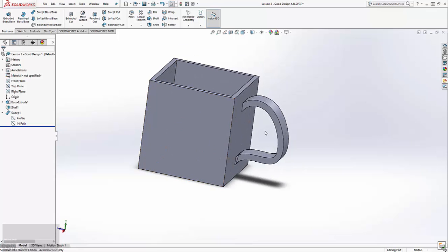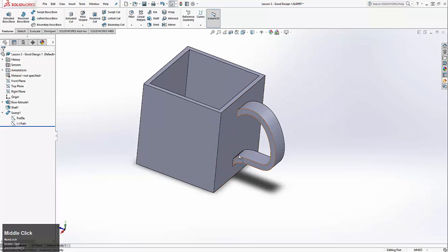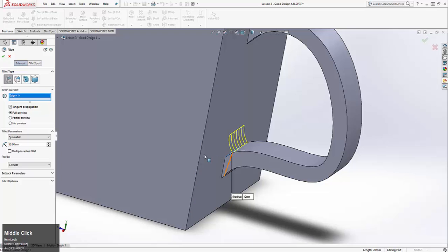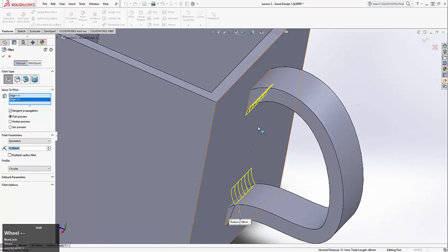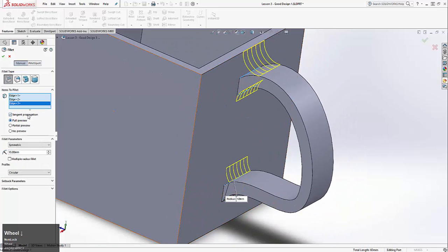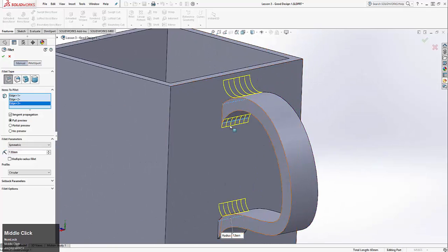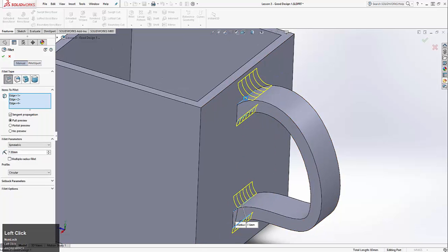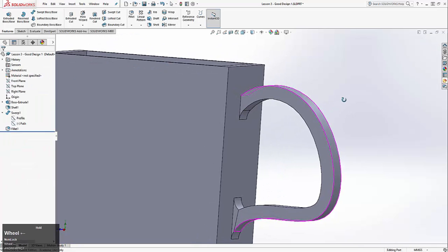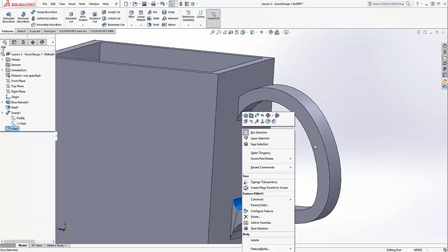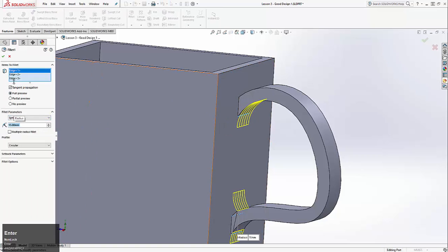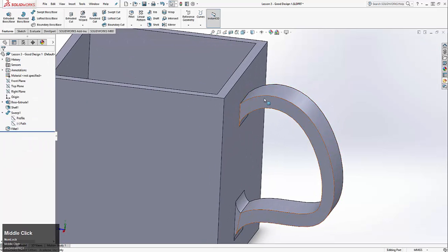Okay, so now if you see these joints, especially right here at the top, and then right there, aren't going to be the strongest, so we can add a fillet. Let's just try 7.5. The fillet's going to be a little bit bigger on an interior angle like that than an exterior one. I'm not going to fillet that one, I'll just leave it. That's fine.